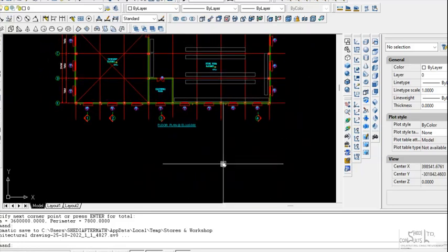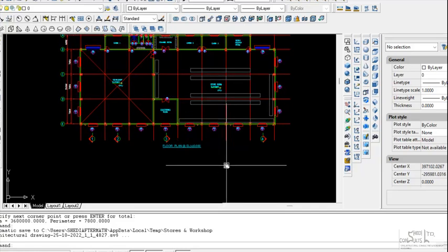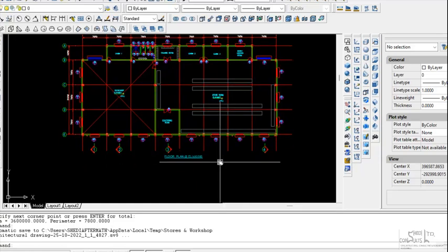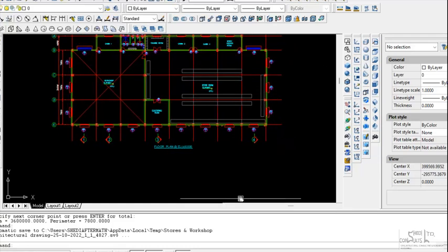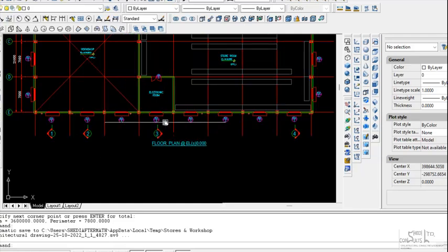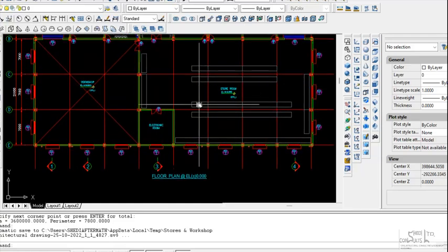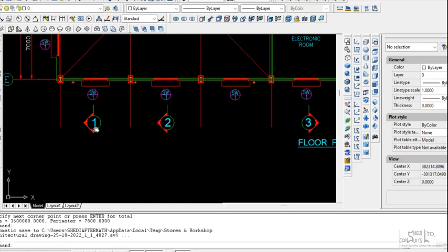Now, for closed buildings, when you evaluate the wind pressures obtained at different elevations, as we have said in previous illustrations and previous videos, the wind pressures obtained in every direction are a function of the crosswind dimension and the elevation. Okay, so it's a function of the crosswind dimension and the depth, the projected depth in which the wind approaches. So you get the external wind pressure coefficient, you get the internal wind pressure coefficient, and they give the resultant wind pressure, and then you obtain the equivalent loads affecting each bay.